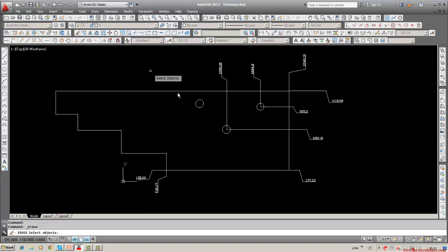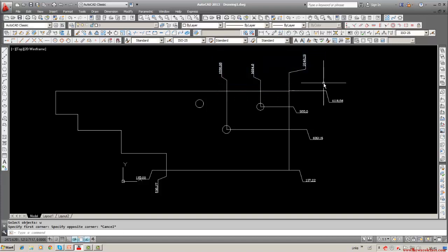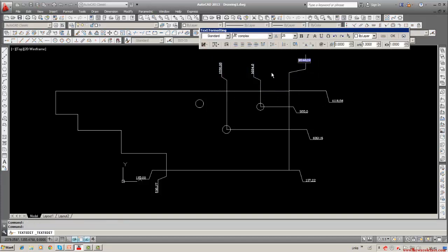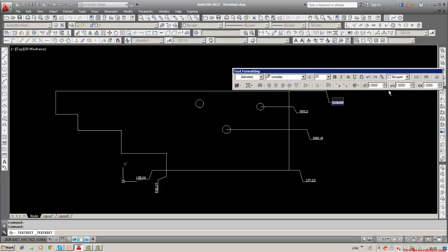So for that, I will tell you what we should do. This is not a very easy method of dimensioning, even though it is a coordinate dimension. But you want the datum to be 0. For that, what we can do is shift the component to the datum line, the center line.